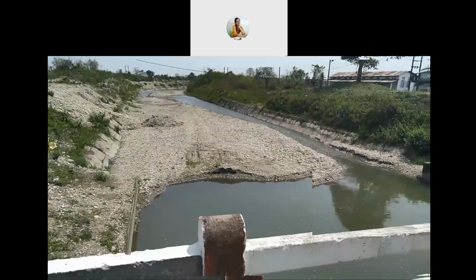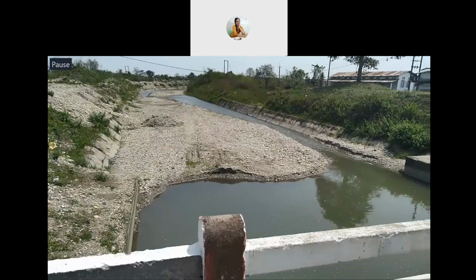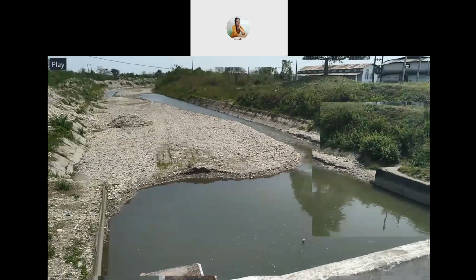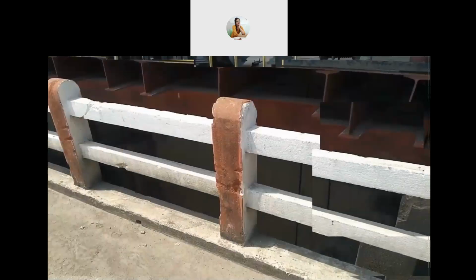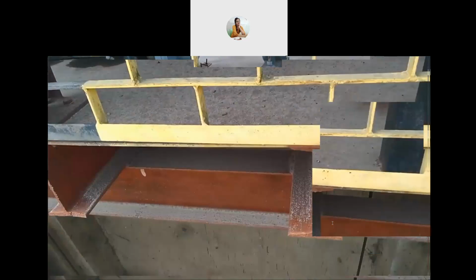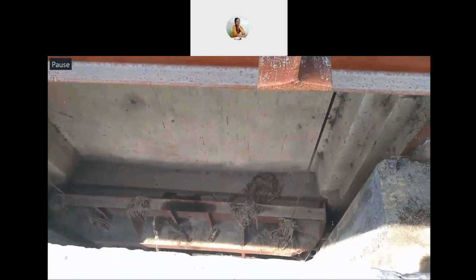The canal also, you can see, is not very well maintained, and there is lots of sedimentation. And as you can see, I guess on the left hand side, there is some erosion from the embankments of the canal also. So that has also filled up some portion of the canal. And these are the gates. These are the machine arrangements which are connected with cables, and these cables run downwards and are attached to the gates. So these gates can be raised or lowered as per necessity.